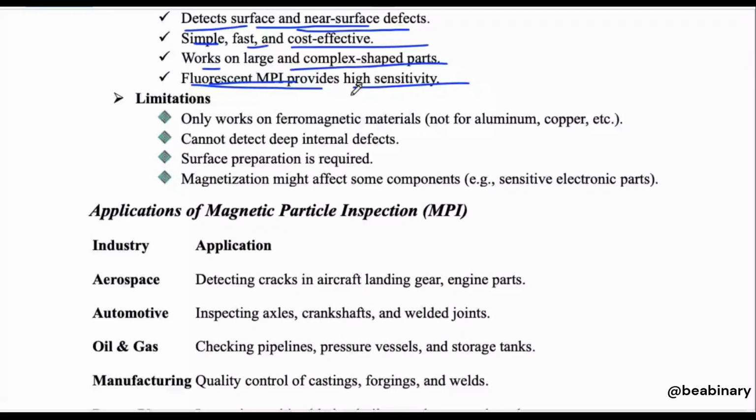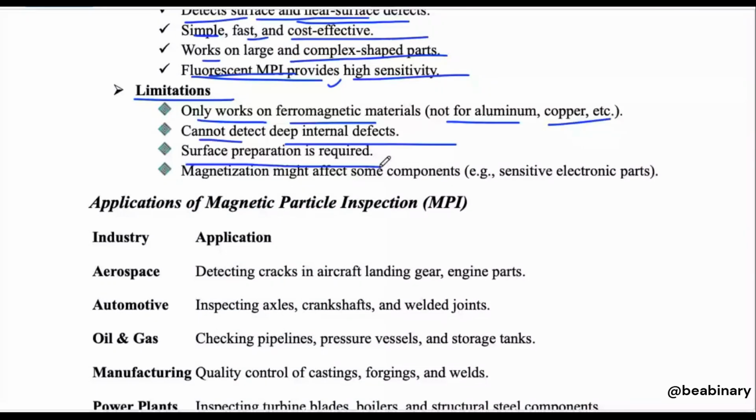It would not be applicable, right? It cannot detect deep internal defects. Surface preparation is required, which is obvious, because we have seen in the steps, the first step was to prepare the surface. We must make the surface smooth and dry.